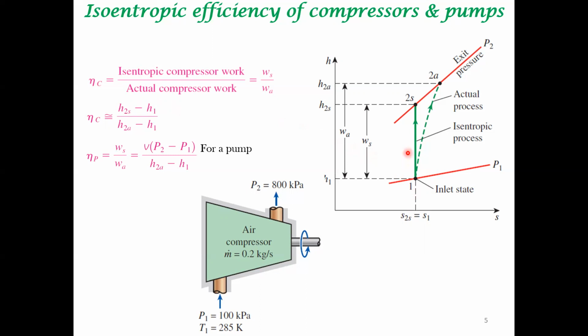The enthalpy of the ideal stream is obtained by enforcing the isentropic condition. This is the enthalpy of the ideal system. The ideal system operates along this line under isentropic condition. But in a real system, the entropy increases, while the pressure P2 is just the same. Therefore, in the Mollier diagram, you would see that the enthalpy is different.